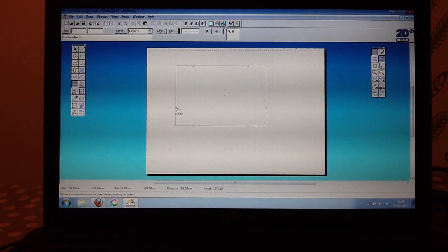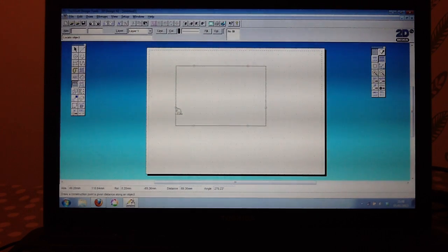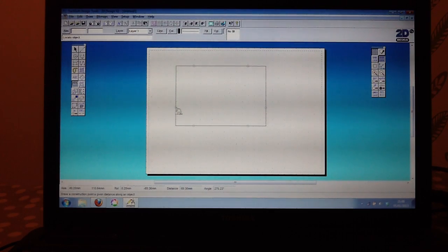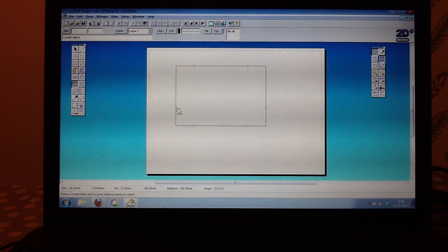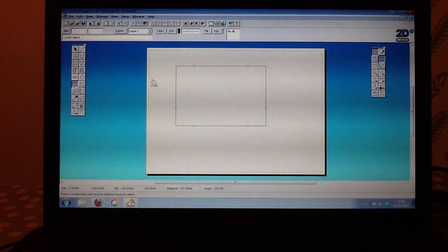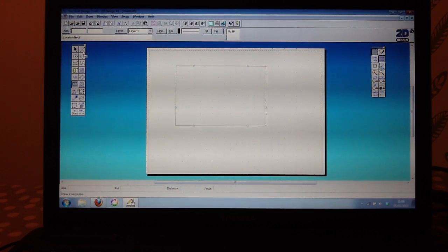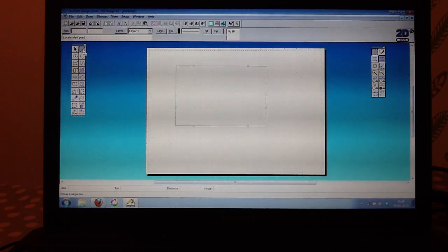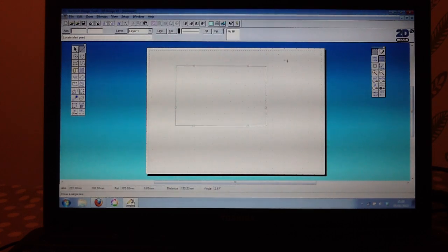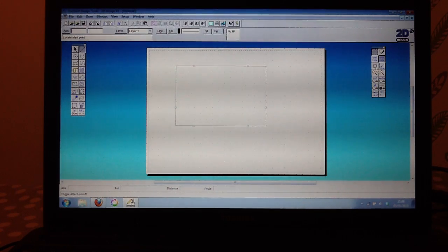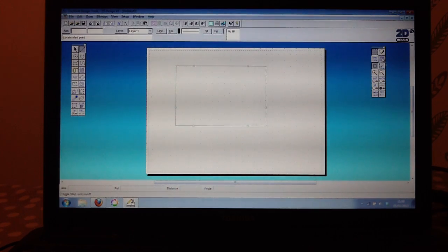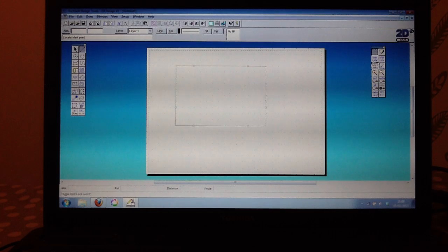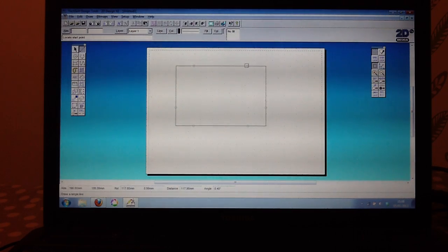This is particularly useful, as we've already said, if you're drawing a really accurate shape, particularly if you're not using the grid lock or you are using sizes which are not in line with your grid. Now if I click off construction points and onto my straight line, and then go across to my Drawing Aids toolbar, and this time click on Attach and click off Step Lock, what I can now do is draw a straight line.